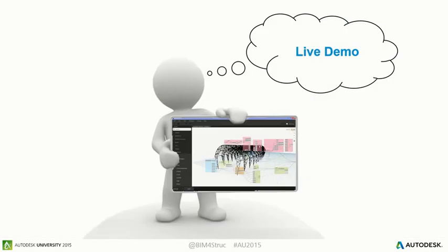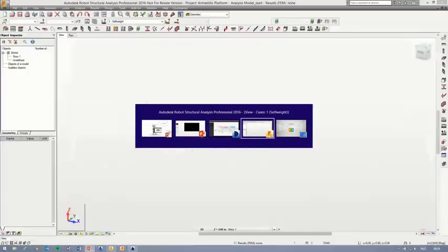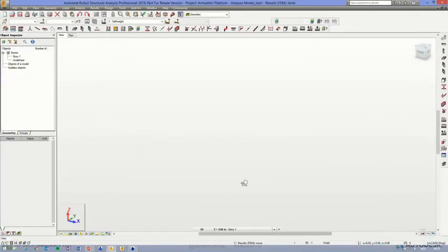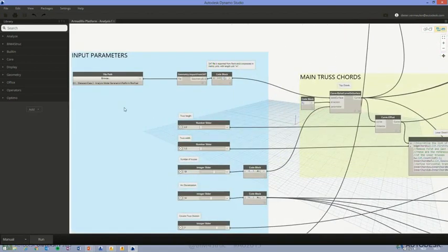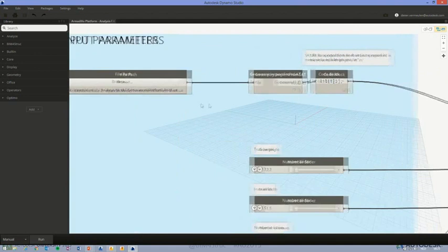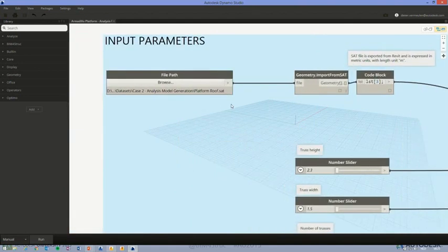But something else that is also important is that you take your list and discretize it in a specific way so that you have the right order. That's very important for Revit. Revit cannot handle all the data at one time. It needs some kind of logical order to generate each object the right way so that it connects well. When you combine structural framings with structural columns and then add braces, sometimes those braces can jump around and go into infinity. We want to avoid that, and therefore you need to make that specific order.